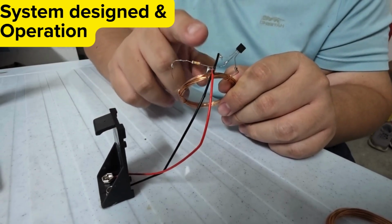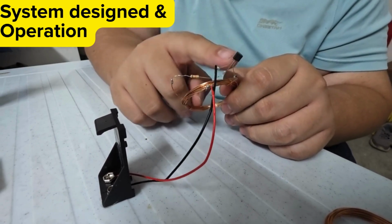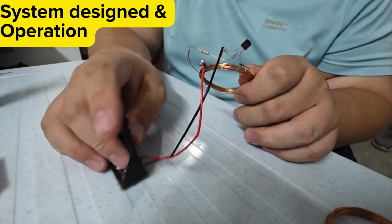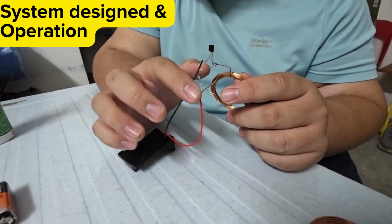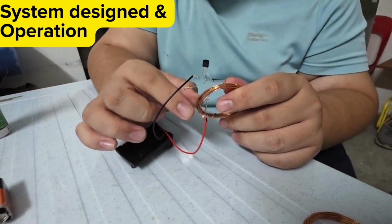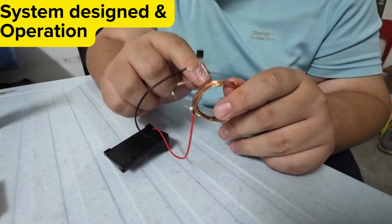The reason for this resistor is to limit the amount of current going into the transistor so it will not burn. Then we take the emitter and connect it to the negative part of the battery holder, and the positive part of the battery holder is connected to the center of the loop here, and the collector is connected to the other end of the transmitter coil.